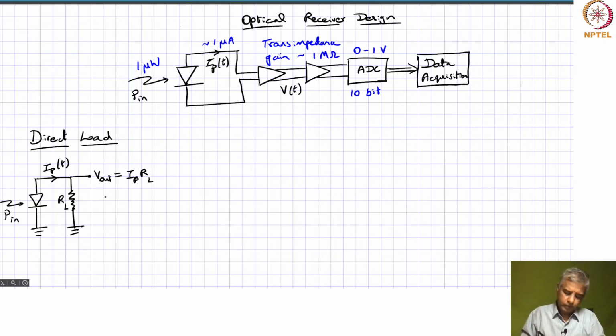Now what really is happening over here? Well, the photocurrent actually flows through this resistor, and so there is a potential difference, which is what you are trying to pick out over here. But in doing so, this potential that develops here is going to act against the potential difference across the diode, or in other words, if you have a certain reverse bias over here, this potential difference is going to work against that reverse bias,